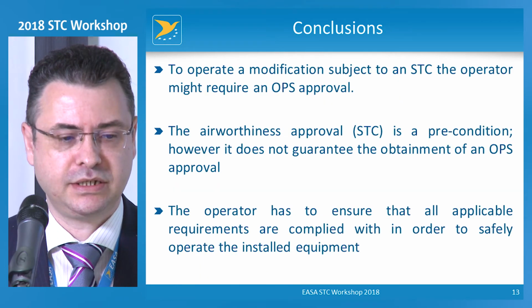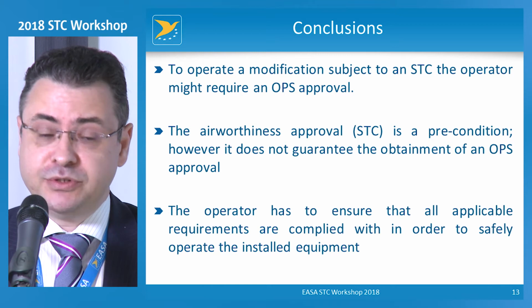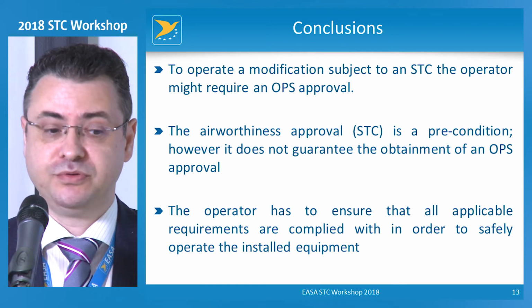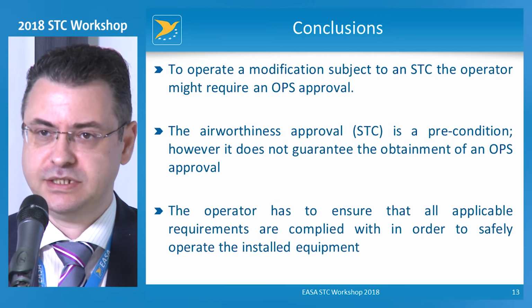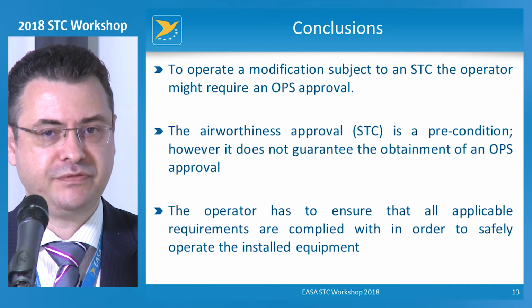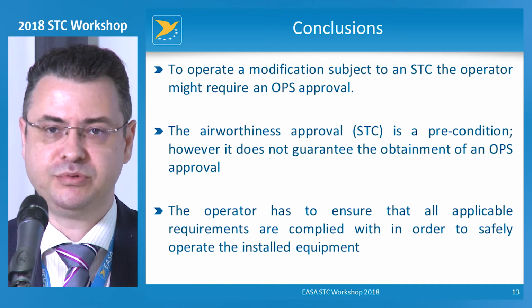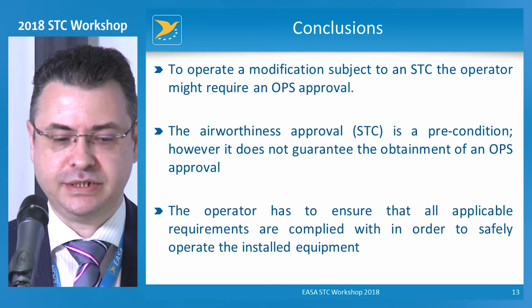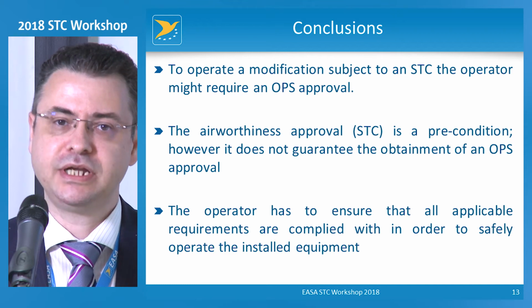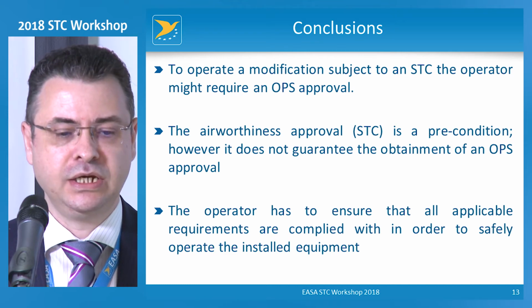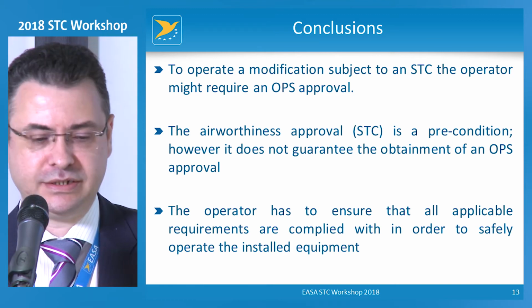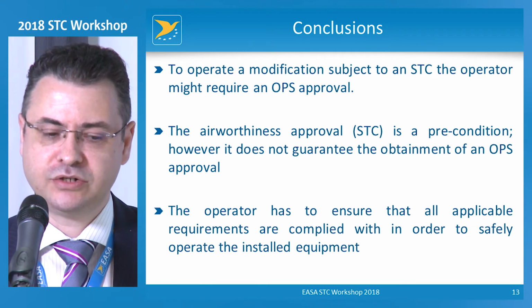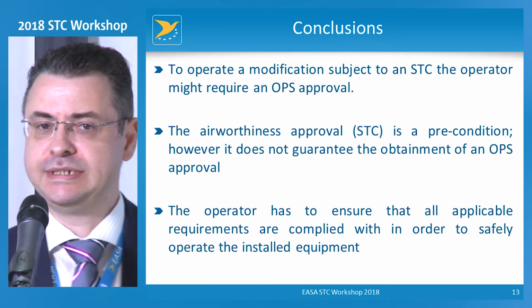From my side, as a conclusion, to operate a modification subject to an STC, you might need to consider that an OPS approval is required. The STC, the equipment, is indeed a precondition. However, in itself it will not guarantee that the approval is issued automatically. And of course, the operator, since it has the direct line of engagement with its competent authority, has the obligation to ensure that all the other applicable requirements, be it on the maintenance side or on the operation side, are complied with in order to safely operate the equipment.